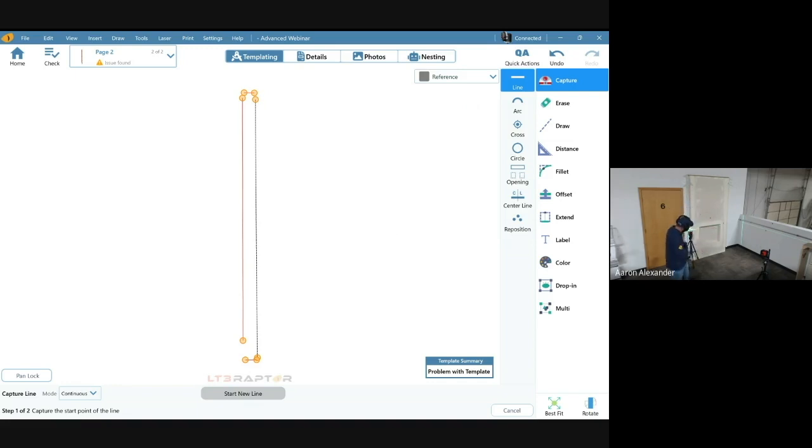So if we shoot the intersection there, and the intersection up there, I'm creating perfectly plumb on the plane that I created in space, and I'm not moving my measurements at all in space, okay? So as you see, there's an intersection right there at the laser. Then there's also an intersection on the wall over there, or whatever it's going to hit in the room. And then, like I say, directly straight up above this laser, there's an intersection there as well.